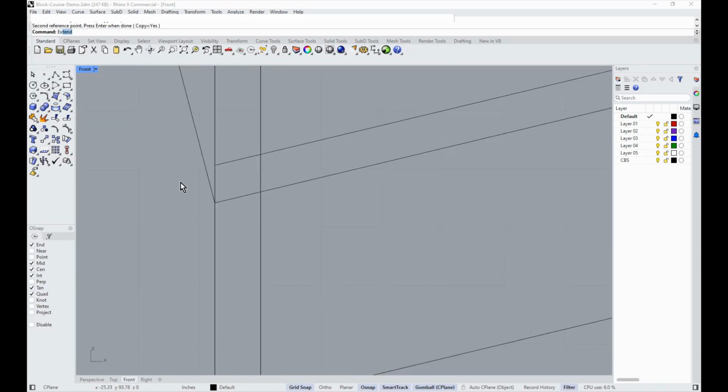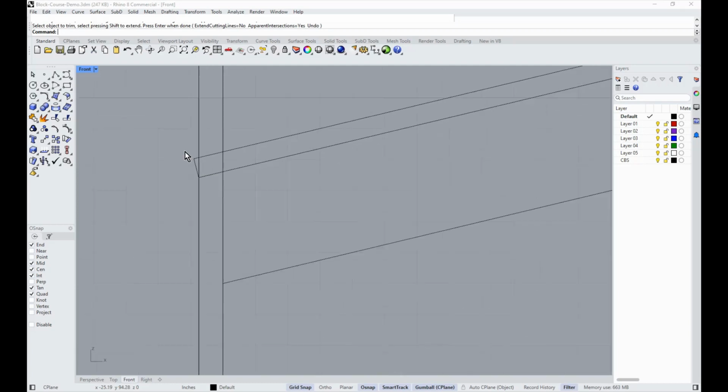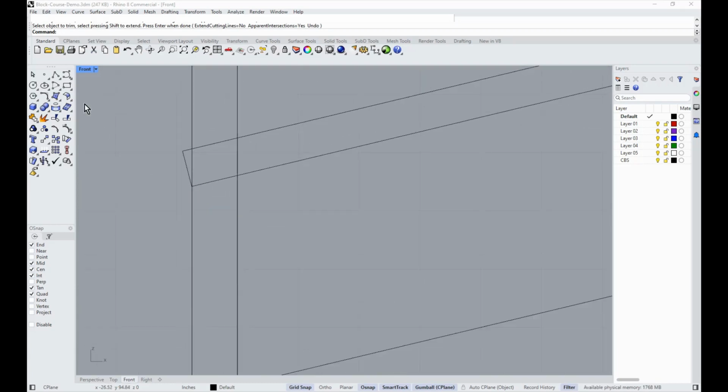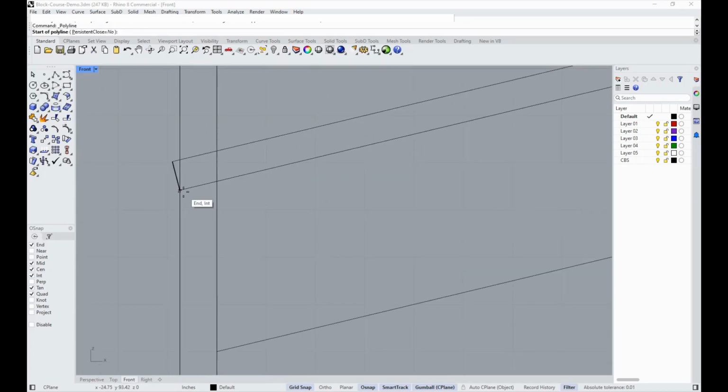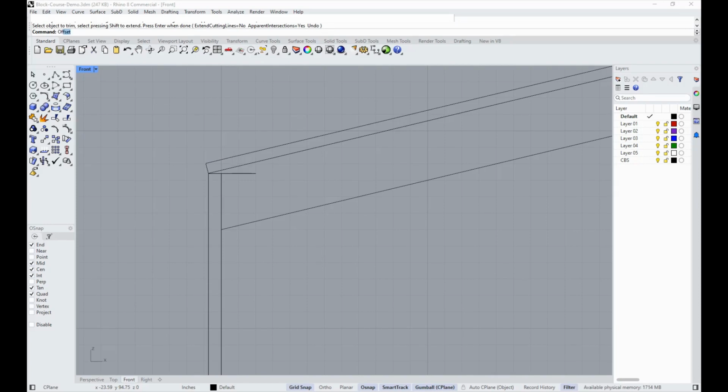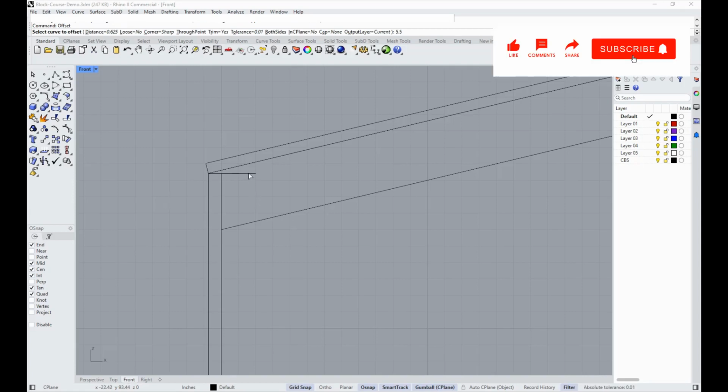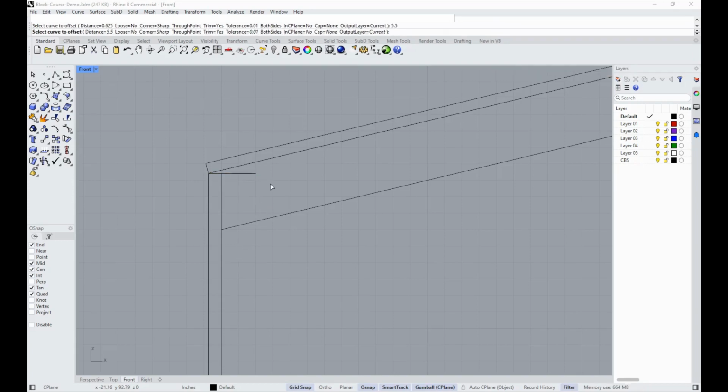This is kind of getting into the weeds, but CAD systems allow you to get into this level of detail without challenges. We have all that, and this also helps you with your offsets and everything. We just want to wrap up the trim. Trim this. And we're going to do offset by 5.5 inches, which is what they call a 1x6 trim board on the end. 5.5 for the offset.